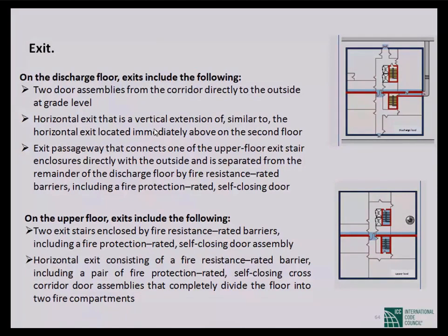One thing you remember, in the upper floor, in the right corner, you see a spiral stair. Remember that if the occupant load is more than 3, a spiral stair is not a fire stair.